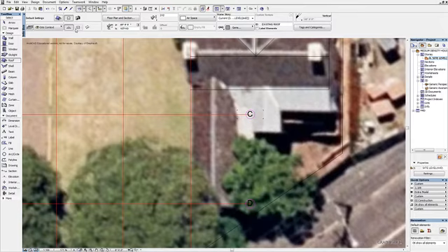What I mean by that is, and I'll just show you now, when we're choosing to draw a roof, first we must choose the construction method. It's rectangular in this case because we're going to draw a rectangular roof here. Never mind about this area here. We're going to fix that using a different ArchiCAD tool, but we're going to draw a rectangular plane like this, and then allow ArchiCAD to marry this roof plane with these single roofs at the correct intersection.